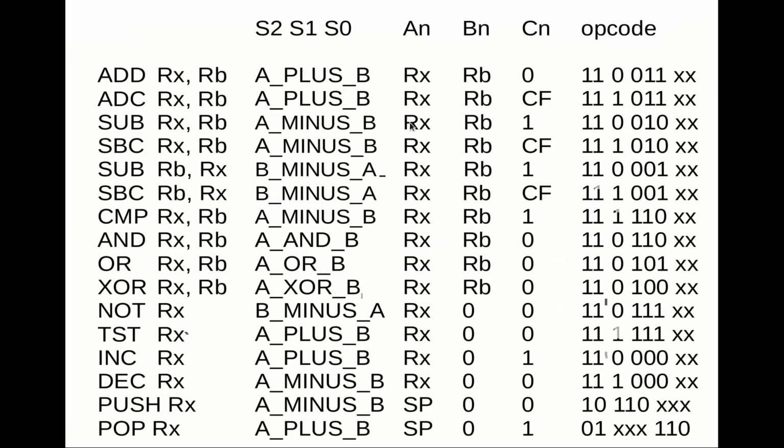And so, all right, here is that same table, and we've added an opcode column here for a basic opcode structure for each one of these instructions. Now, perhaps you'll remember from our discussion when we were talking about the general architecture of our ALU, we came to the conclusion that since we have to encode them basically in 6 bits, because these first 2 bits will be set to 1, 1 to say we're dealing with an ALU class operation,